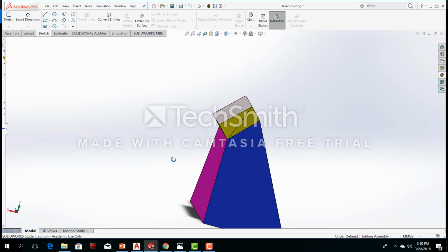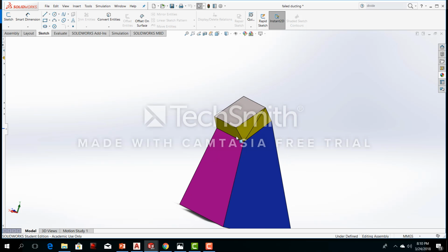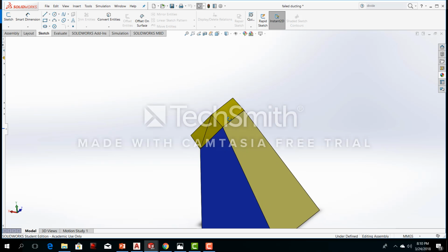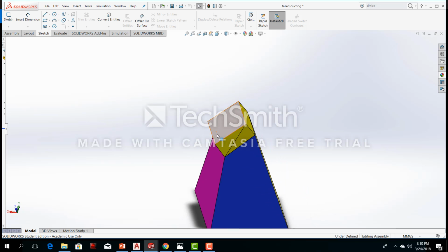The key principles I've been looking at here on this one were triangulation, so I can take my 3 points and I can find where they are. I can also use my center axis here to bring it up and find where my rectangular piece is intersecting, and I can draw in my real line of intersection between my new transition piece and my ducting, which is just here, which is going to be identical to that of the area of the ducting.